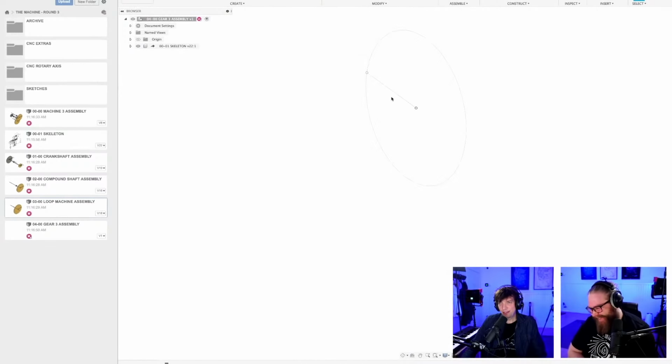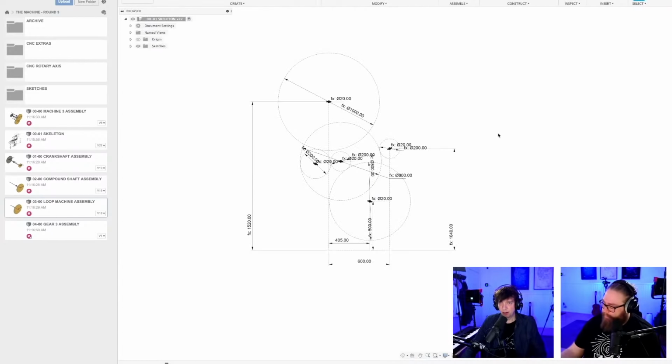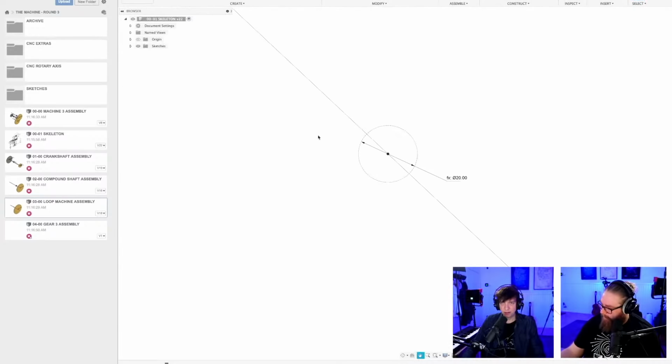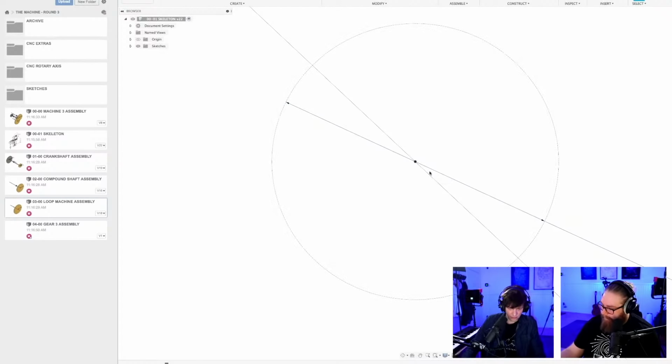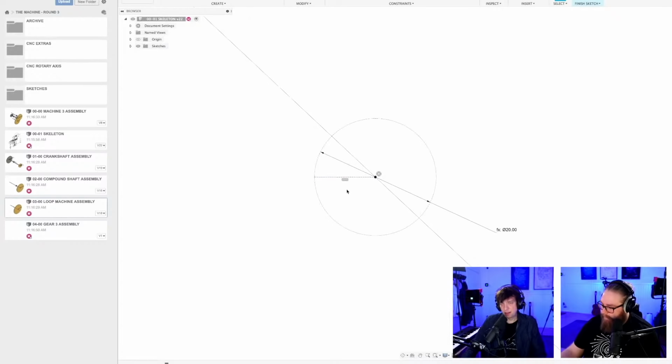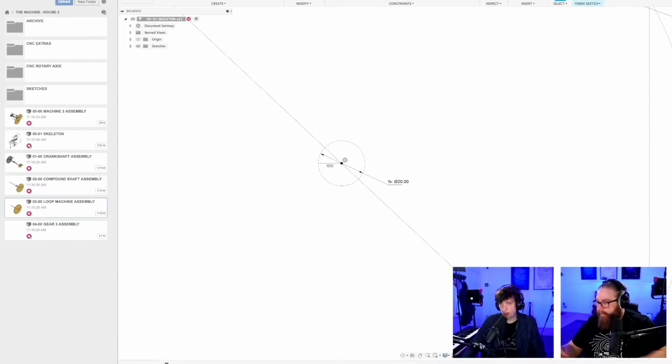I actually forgot this little line. This small little line is very important in the pivot point of all these gears from the skeleton. I've seen that I have forgotten it on this gear, so I'm gonna add it right here. Oh, I have to go into the sketch first. Just adding a vertical line there. And that's the line I'm basing the sketch planes on.